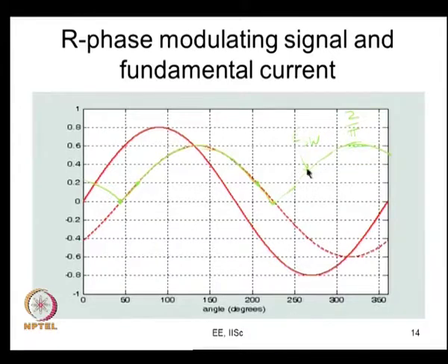On the other hand, if the current amplitude increases, for example, if the current amplitude doubles, the corresponding switching energy loss peak value will also double. Therefore, the average loss will double. But when the current amplitude is the same, given as some 0.6 per unit here, but the power factor changes, then the switching is not going to change. Thus, for any particular sine triangle PWM or any continuous PWM, the switching loss does not vary with power factor, as we already discussed yesterday.